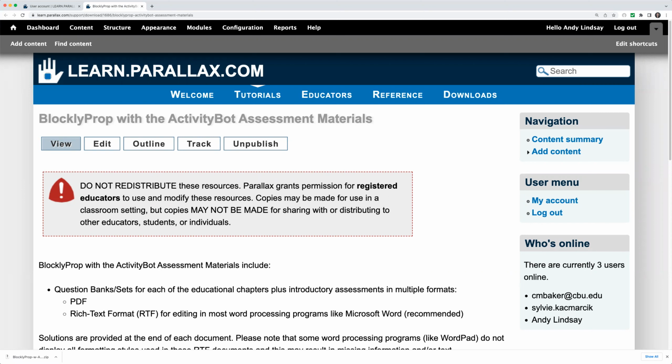So if you have not already tried one of those, be it whiskers or light following or infrared navigation, definitely take the time to go through and do one of those chapters. If you're new to electricity and electronics, I recommend the whiskers because that's where we always start with the students as a first circuit, because it's a very tangible thing where you push the whisker against an electrical contact and you can see the change from 1 to 0 when you do that. And so that's an important one if you're going to try one.